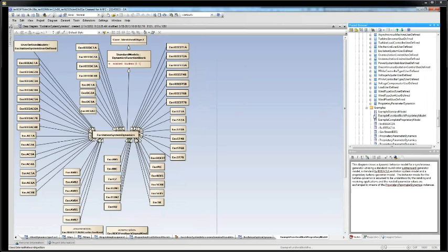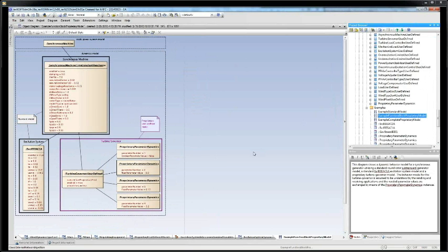So this was the way that a dynamic model, a fairly simple one for a synchronous generator, could be defined that had a proprietary turbine governor model in it. So it's a standard excitation system, a standard synchronous machine model, but here's the turbine governor, and it's proprietary, and you're passing 4 specific parameters that the sender knows about and the receiver knows about.